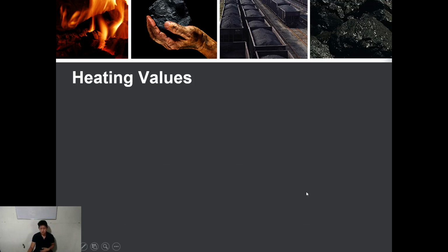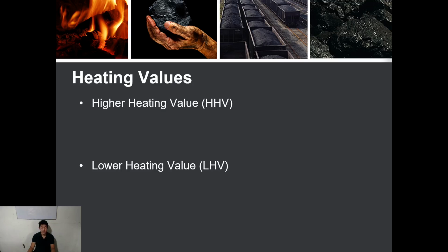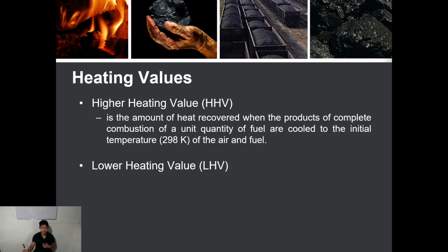Okay, so different fuels are characterized by their heating value. There are two types of heating values: the higher heating value and the lower heating value. This heating value is the amount of heat that is recovered when you combust 1 kilogram of fuel and allow it to undergo complete combustion.